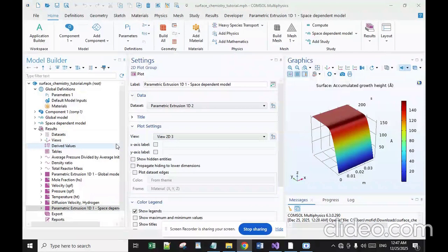The next is remote plasma enhanced CVD, similar to PECVD except that the wafer substrate is not directly in the plasma discharge region. Removing the wafer from the plasma region allows processing temperatures down to room temperature. The next one is low energy plasma enhanced chemical vapor deposition, or LEPECVD.